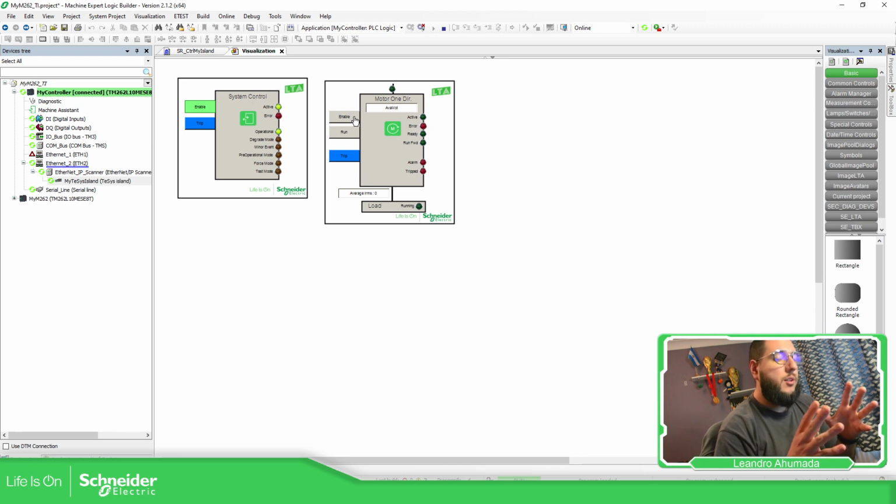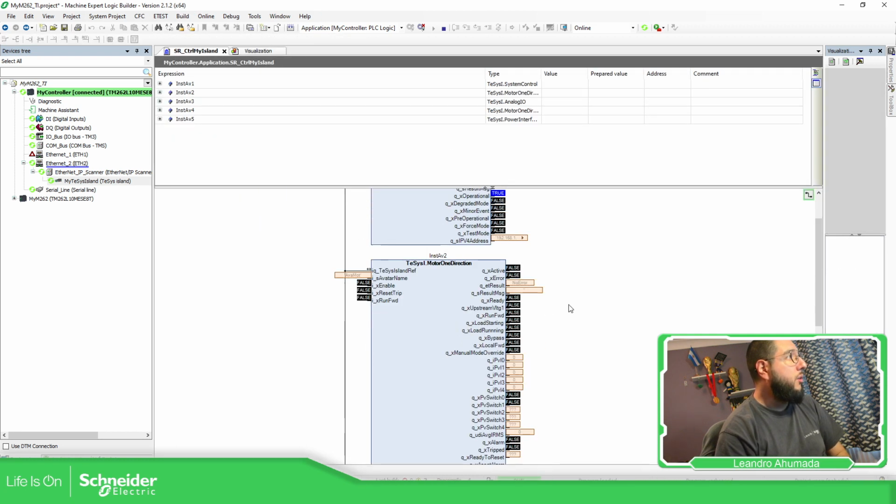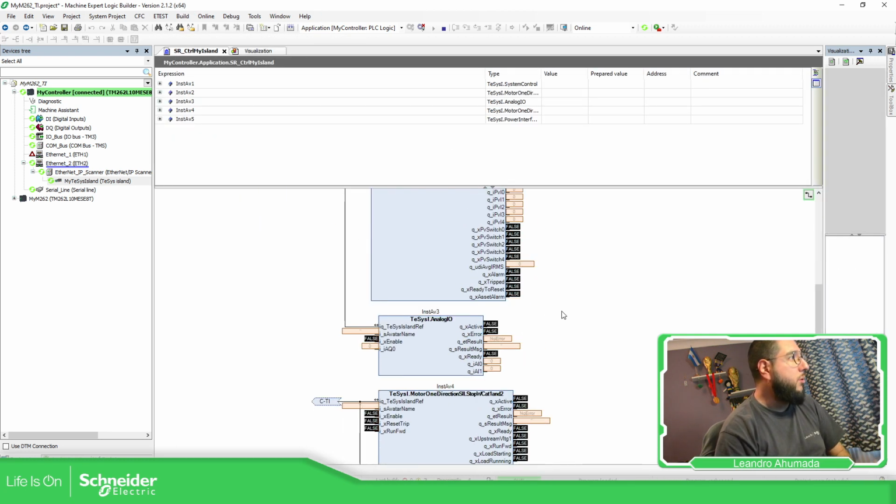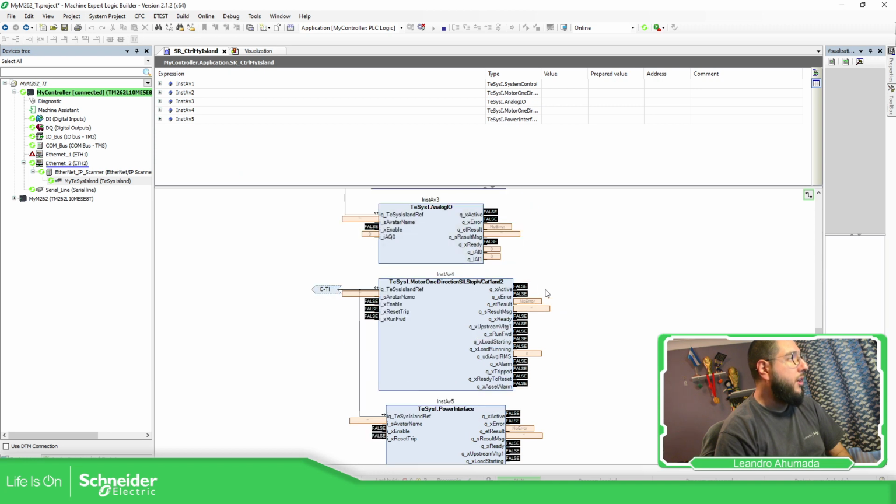So a few things that in this particular video, I already explained how to do it on EtherNet. There is something that you need to be aware of: in order to use the library in Machine Expert, you need to always check the DTM and the firmware compatible with the version of the machine expert that you're using. Because that can create some kind of confusion. There are some incompatibilities depending on the firmware and the library, so you need to be aware of that. So in this case, now I'm going to show you that we can work without these things. So let's see.